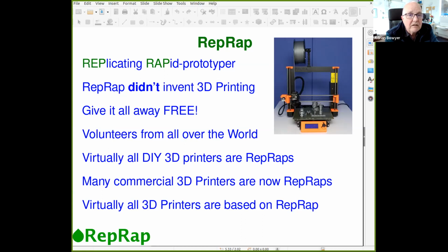And he had the idea that you could shine a laser into a tank of monomer, plastic monomer, and where the laser beam hit the monomer, it would cause it to polymerize by photopolymerization and therefore set solid. And he said that you could move the laser beam about and print out a 3-dimensional shape in the volume of this liquid monomer. And of course, that's one of the first types of 3D printing that was actually achieved, even though he didn't think it was a serious possibility at the time.